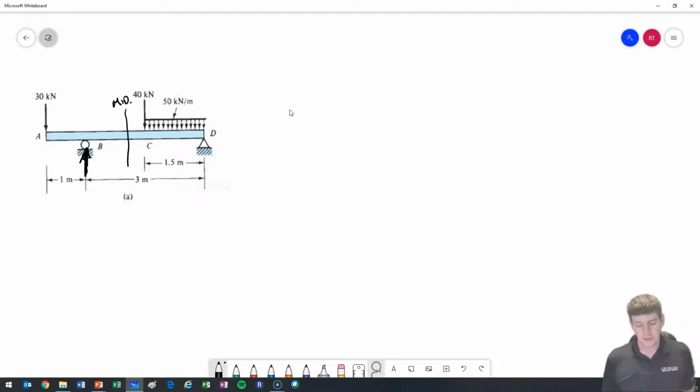Okay, so as I said, B was actually fairly easy, and let me explain why. So if we cut the beam, normally we're going to go to the extent of finding out all of the external loads happening on this beam and then be able to solve it. But actually, if we look at B, when we cut it, we have a free end. So that end is overhanging, and it's not much different than a cantilever beam.